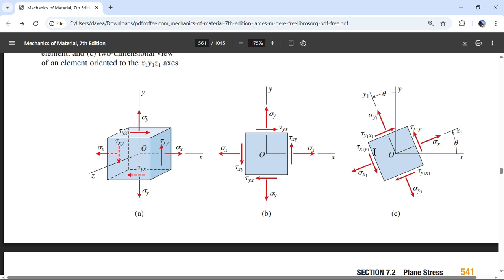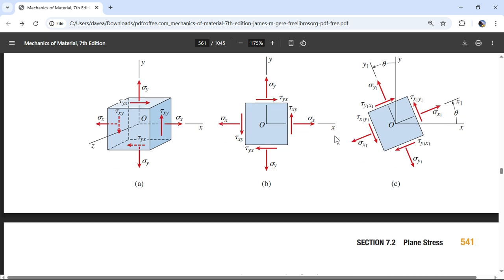All right, hell yeah. So we know the stress element has equal area, so it's synonymous with equal force. A force up matched with a force down is Newton's: the sum of the forces in the y direction is 0. But that's going to cause a torque. It has to be balanced by the only other places we can put the forces, which are synonymous with these stresses, same area, and those are going to have to be equal. So cool. All right, hell yeah.